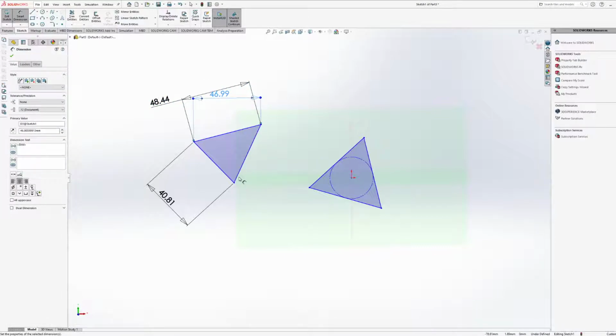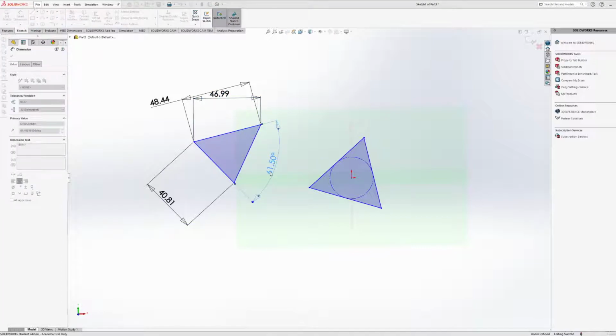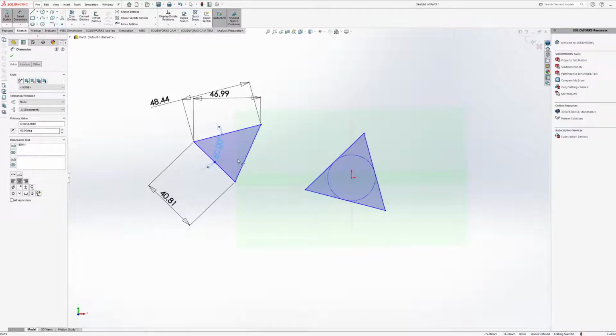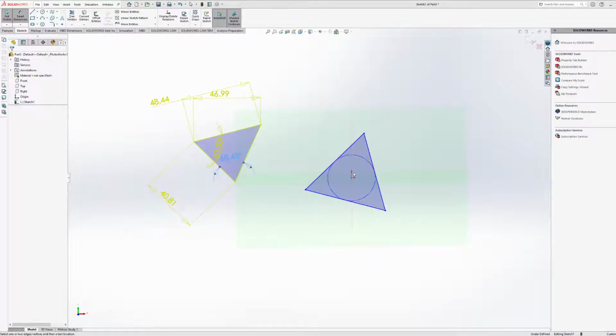If you want to do angles as well, which you can do, I would just click on both of those two different sides, and it will automatically define that angle as some degrees. So let's say I wanted this one to be 60. Watch me make some sort of really poor triangle. Yeah, something like that, where it's already defined.